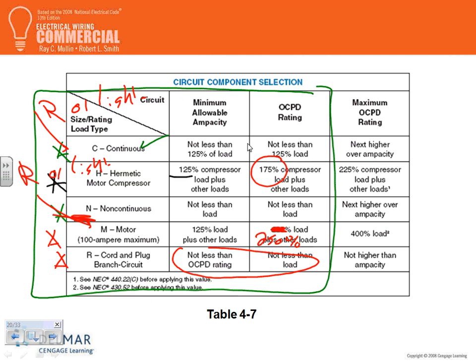You're not going to be able to plug it into a receptacle that's not rated for it anyway, because the plugs are different. If you have a 50 amp machine, 50 amp 3-phase, the plug will be 50 amp, the machine will be 50 amp, the cord will be 50 amp, and the cable coming to it, the circuit, will be 50 amp. So all rated for that particular machine.